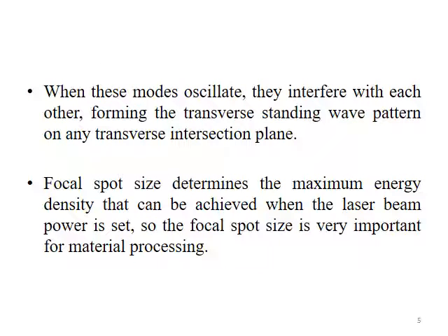When these modes oscillate, they interfere with each other, forming the transverse standing wave pattern on the transverse intersection plane. The focal spot size determines the maximum energy density that can be achieved when the laser beam power is set. So, the focal spot size is very important for material processing.